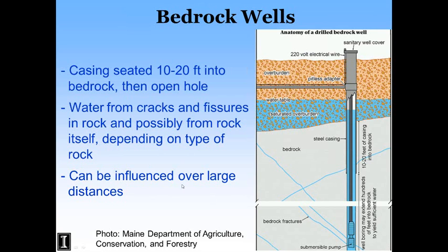And so the deal with fractured rock is you may have fractures that run typically in certain directions. And so when you pump your well, you may be pulling water from the north from a half mile away eventually, whereas from the west and east you're not getting water from more than a few feet away because there are no fractures running in that direction, and water is going to flow with a path of least resistance, and an open fracture obviously allows water to flow freely through it.